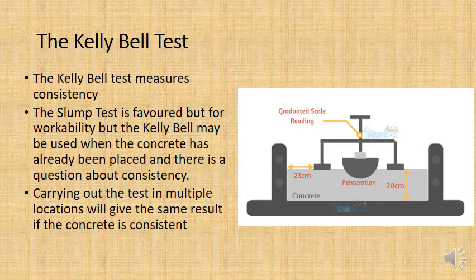I needed to check the concrete mixture and do a slump test and make sure that it was workable enough, and then say, okay, you can pour the concrete. If it wasn't workable enough, they wouldn't have been able to compact it, and that would have meant there would have been voids inside the wall, and it would have led to honeycombing. More on that later.